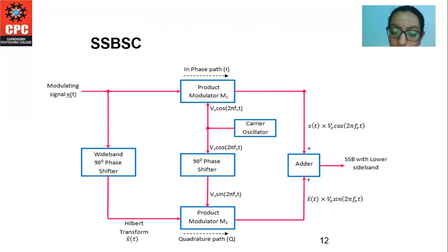That is, as far as the transmission of information is concerned, only one sideband is necessary. The other sideband and carrier can be eliminated or suppressed, we can say. Therefore, the communication channel is required to provide only the same bandwidth as the baseband signal when only one sideband is transmitted. The modulation system is called a single sideband system.